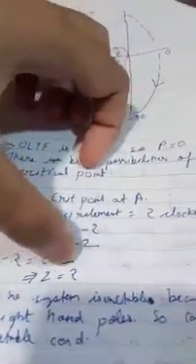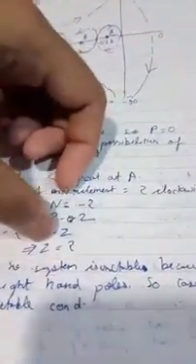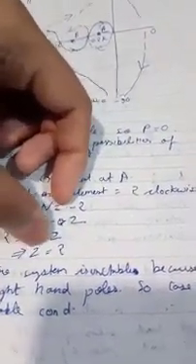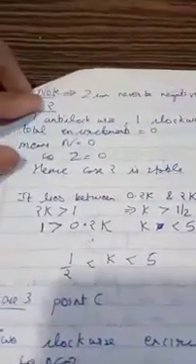And as per Nyquist stability criteria, n is equal to p minus z. So minus 2 is equal to 0 minus z. P is equal to 0 as we have already seen. So the value of z will be 2. So the system is unstable because the number of right hand poles is 2. So case 1 is unstable condition. And we can see that the Nyquist gives absolute stability because it says that this system is unstable because of two right hand poles. So Nyquist and Routh-Hurwitz provide absolute stability. Polar plot provides only relative stability. And note that when we solve for z, if we are using the right approach, then the value of z can never be negative.